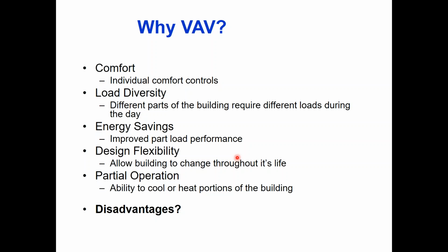If I was to do that with regular constant volume equipment, I would need to know where I wanted each of these things to be inducted to. With VAV systems, what I can do is build that core and have a loop going around each floor for the duct system. Then as the tenants build out their area of the building, they could tap into that duct system and pull their air from pretty much anywhere on the duct loop. And then if somebody moves to a different area or different zone, and you say, you know what, we're going to make this area a copy room, we need more cooling, I could put another duct run in there and take it away from something else.